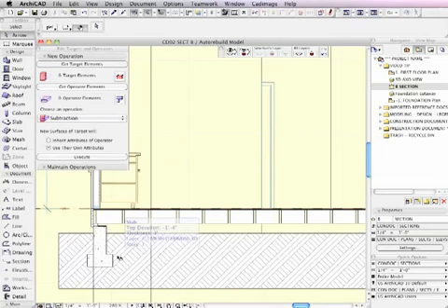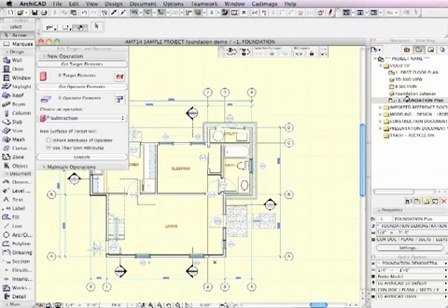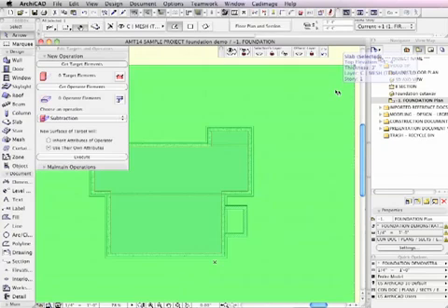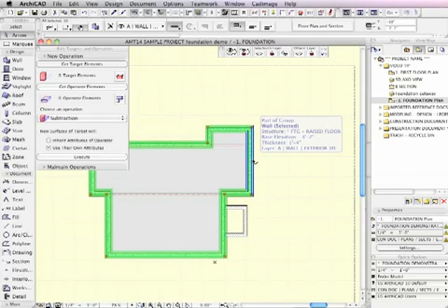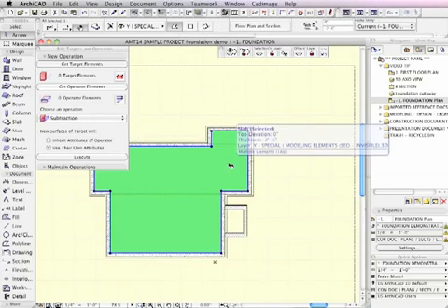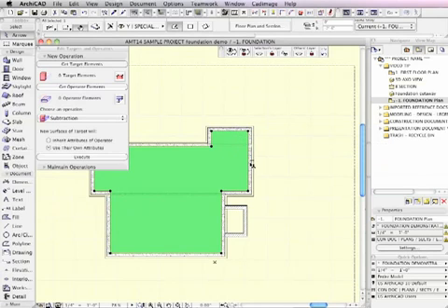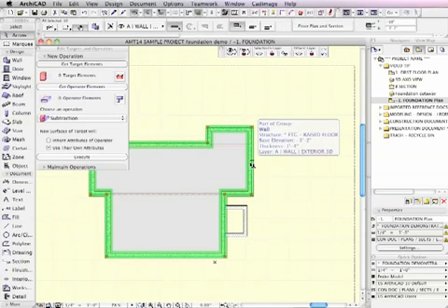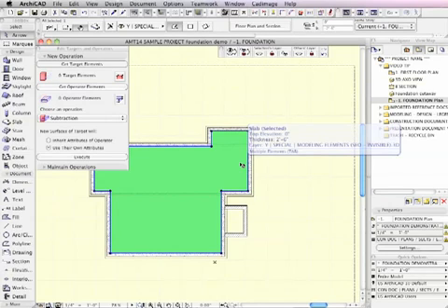Now we're going to go on and create a crawl space. On the foundation level on the plan, you can see here is the terrain that is created with a slab. Here are the stem walls and footings, and here is a special purpose slab that I've created that actually extends to the inside face of the stem wall. You can see how they go in a little bit further than the gray area.